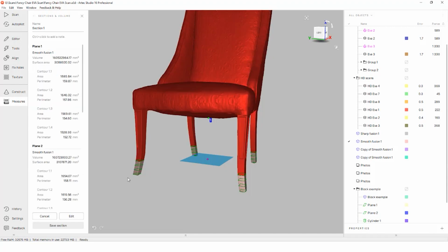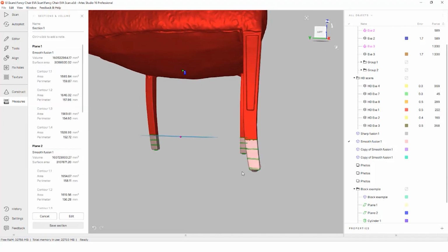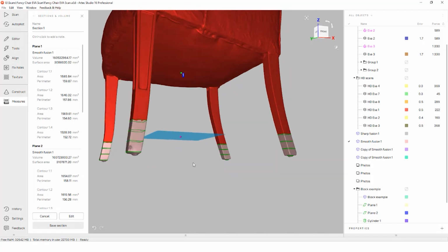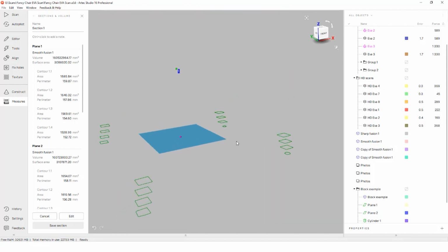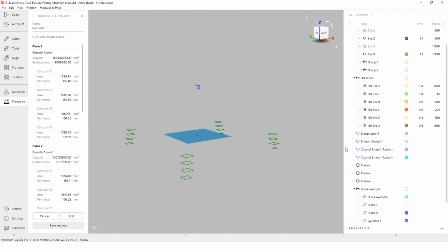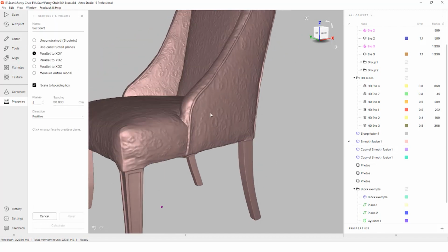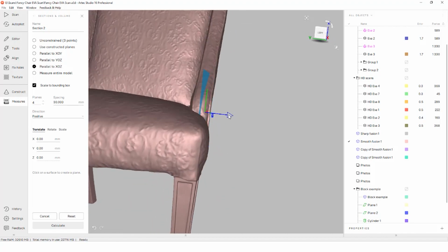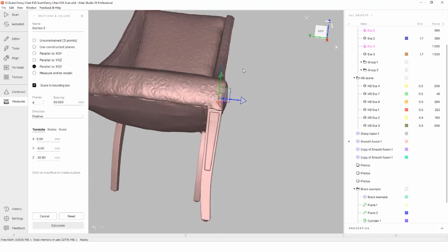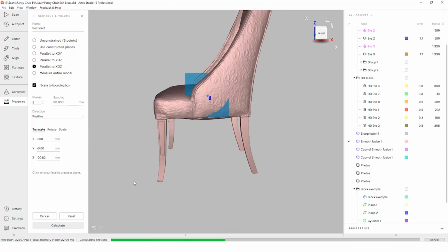When we click Calculate, we'll get a bit of information about what has been extracted from the mesh. We get not only the volume and surface area of our highlighted part of the mesh, but also a 2D sketch based on where the mesh intersected with that plane. We can save this section and export it as a DXF and import it into other CAD softwares as polylines. These are excellent for being used as a reference when making proper sketch features.